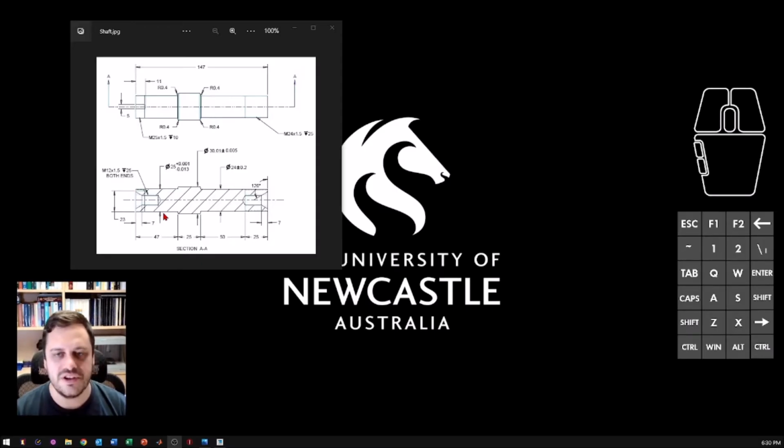There's a few things on this particular drawing that we're going to run through with this model. The main thing that we want to think about is, when you're doing your sketch for the revolve, you effectively take a half sketch, because we then revolve it around 360 degrees. So in this section view of the shaft, if I look at this center line running through where I'm hovering over with my cursor at the moment, everything above that line is what I want to physically sketch, and then I'm going to revolve that around 360 degrees.